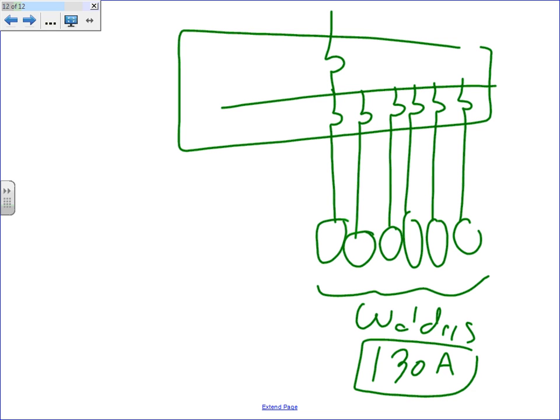Now I decided to throw in a bunch of lighting circuits and receptacle circuits. Look what I'm going to do. I have a bunch of branch circuits of lights, and I have demand. Everything is demanded. I applied 125% to everything. I added a 10 kVA load here; after I demanded it, I increased it by 125%. This is for light.